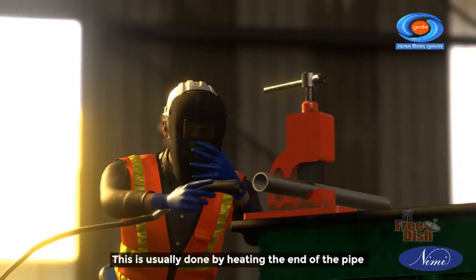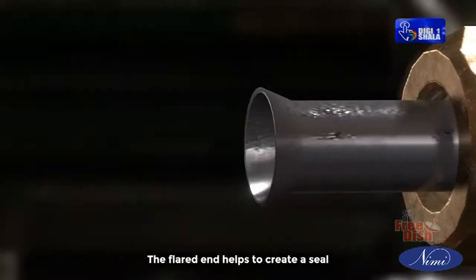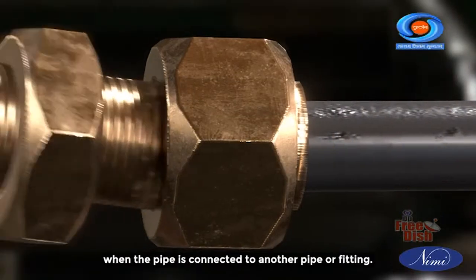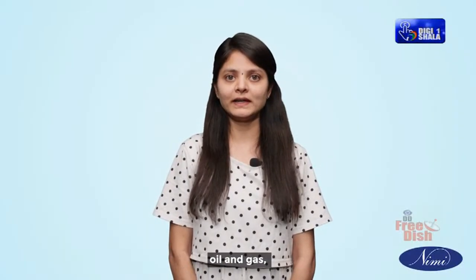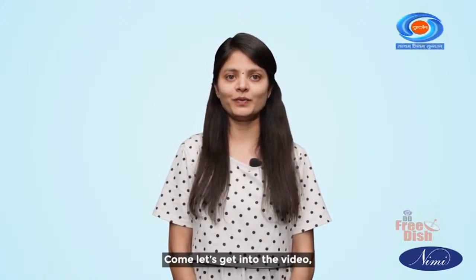This is usually done by heating the end of the pipe and then shaping it with a tool. The flared end helps to create a seal when the pipe is connected to another pipe or fitting. Flaring is used in a variety of industries including plumbing, oil and gas, mining, and steam systems. Come, let's go into the video.